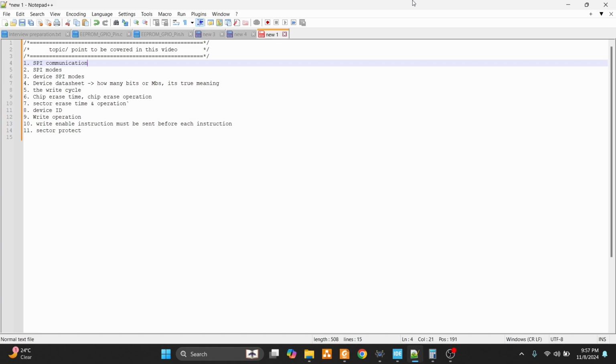So these 3 pins are what we can call additional pins, as we have seen that we are using the push pull transistor, right? So the main advantage of SPI communication is that it operates in push pull mode, push pull transistor mode. So the operation is faster as compared to open drain. Second thing is we can connect as many devices as possible, so there is no limitation. The disadvantage is that as we go on increasing the slave devices, the number of chip select pins will also go on increasing, so that will limit our other peripheral interfaces. So that is one limitation for SPI communication.